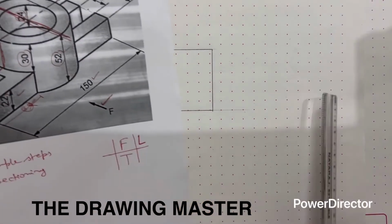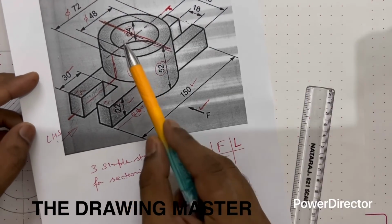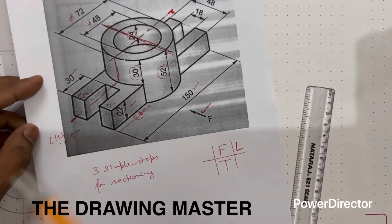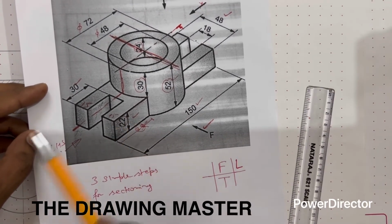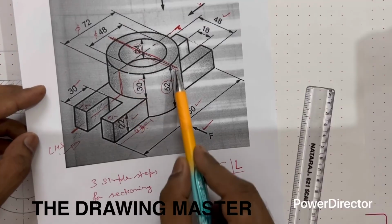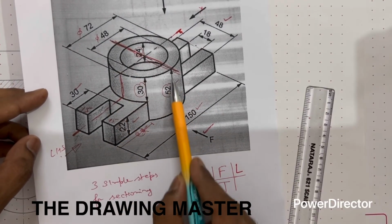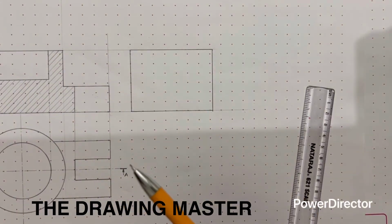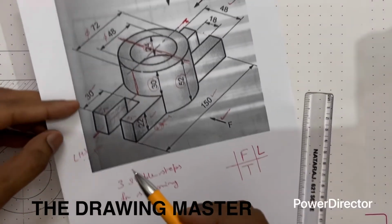I'm repeating this again. Only 3 simple steps are there in this trick. Step 1, just draw the outline. I'm not asking you to draw any hidden line, any orthographic projection, any internal edge, nothing. Very simple, just draw the outline. So from the side view, this dimension will be 72 and this is 52. I'm not asking about this line. This is the outline.